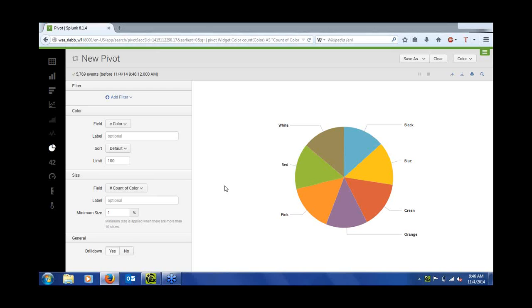The Universal Forwarder has the ability to utilize SSL to authenticate and encrypt data connections between your operations network and your IT infrastructure that Splunk is typically installed on. It also gives you the ability to persist and buffer data locally in case you have intermittent connectivity between KEPServerEX and the Splunk Enterprise installation.